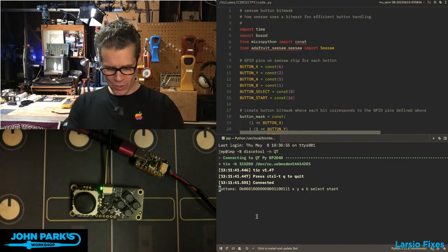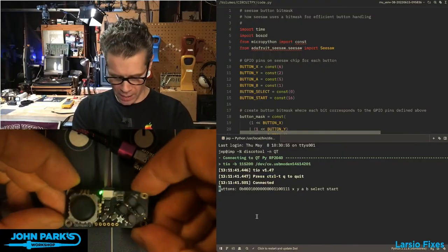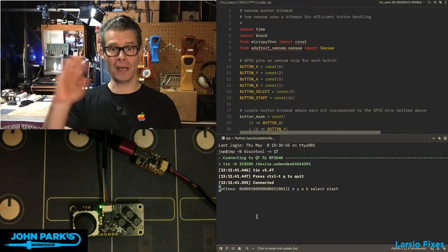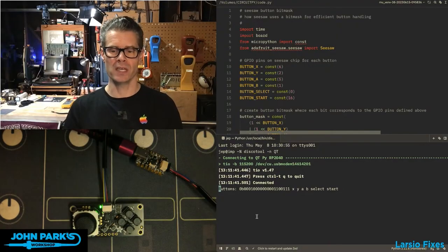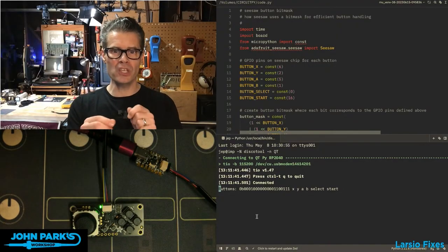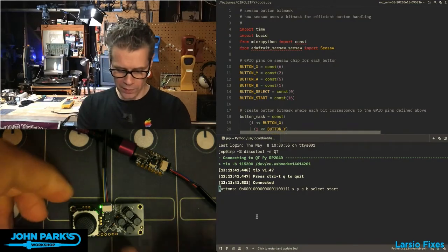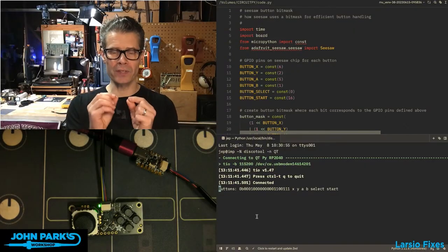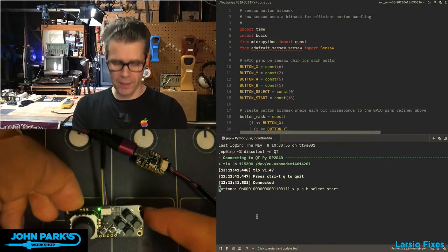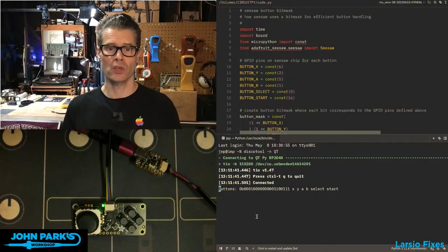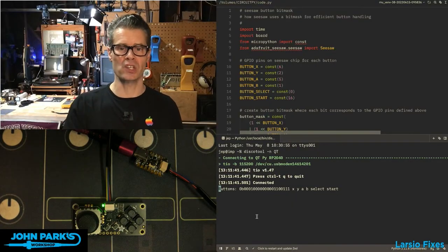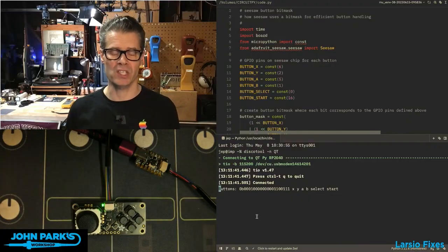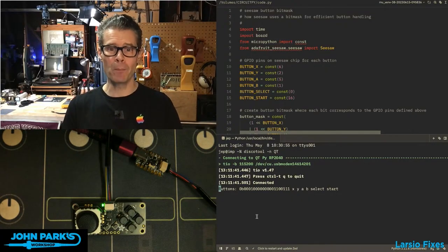So when we're using a Seesaw chip, such as the one on this little Gamepad QT plugin, we get the benefit of talking to our microcontroller over I2C and taking care of little GPIO things right on board with the little Seesaw chip. And to keep things fast, we can send bundled up little messages about what's going on this external board, so that we don't have a whole slew of messages to get across the idea of, let's say in this case, 6 different button states. So the way this is done is with a bitmask.